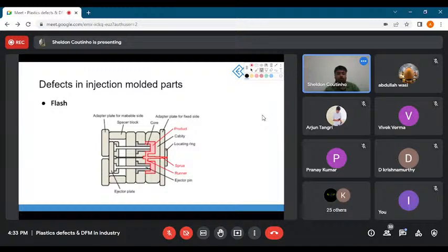So again, when I showed you now, this is a part of design for assembly, or DFA. So as I told you, you can have it arranged like this, three, which are equidistant angles from each other, say 120, 120, 120. Rather than having everything at 120 degrees, the more clever form would be to have it something like this. So here you will have maybe 180, here you will have 90 and 90.